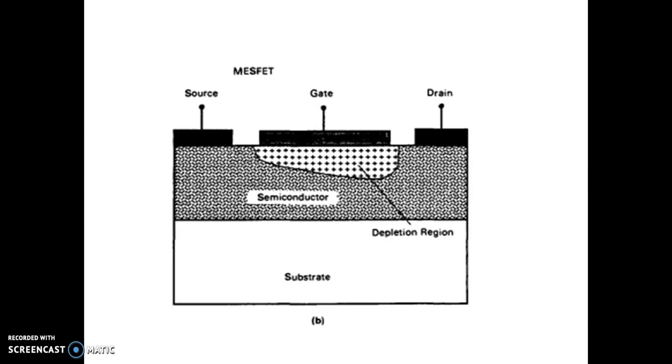In this figure, the basic schematic diagram of the MESFET is shown. Here, the channel can be partially or totally depleted by the gate voltage and by the built-in voltage of the Schottky contact forming a gate. Here, the channel, the source and drain, two ohmic contacts, are on the sides of the gate terminal.